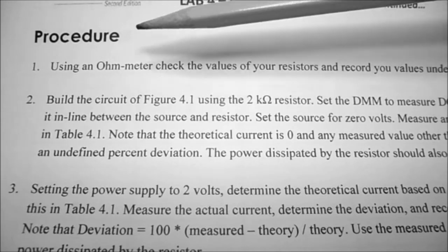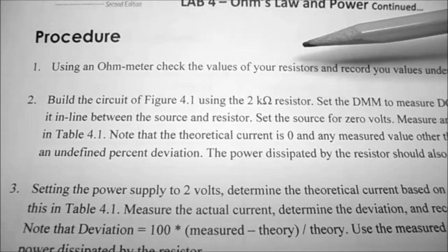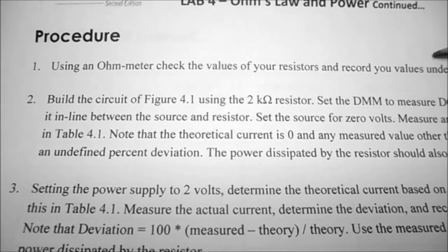So the first thing we're going to do is use an ohm meter to check the values of the resistors and record your values under equipment.